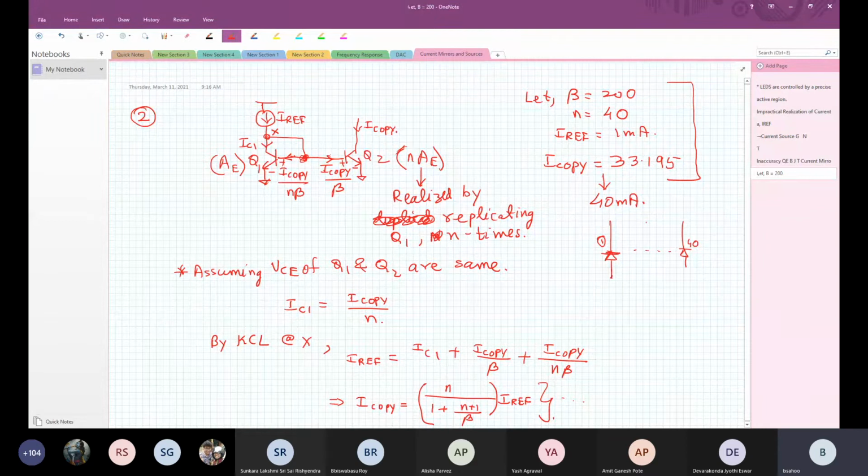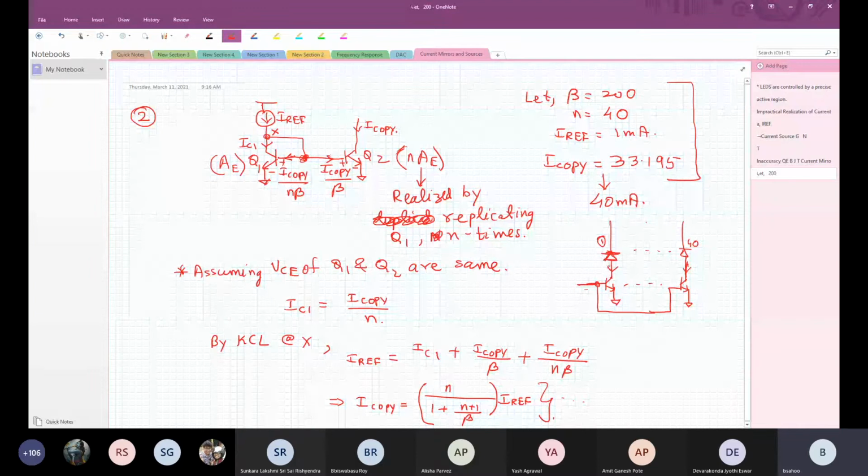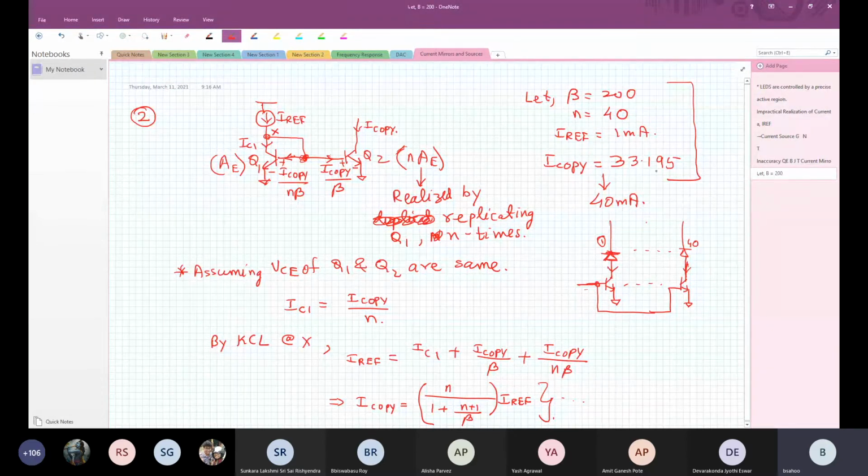Now these are all driven by current sources. They will all be driven by this current source. I want exactly 1 milliamp to flow in each one of them, so that I get a certain intensity and brightness in the display. Unfortunately, I'm getting almost 20% reduction in the intensity.